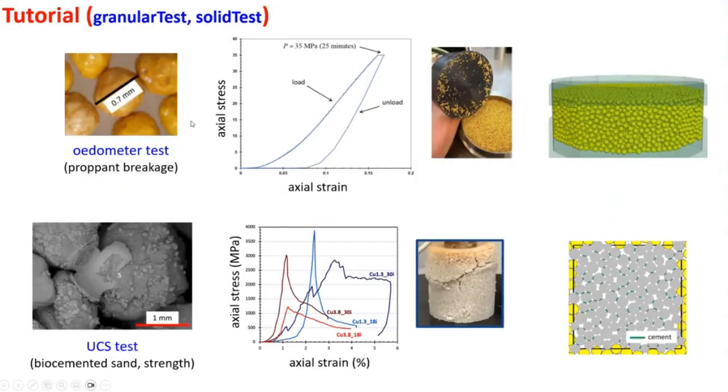We're going to turn that thing into an oedometer test, and we're going to bond it, and see if we can get this kind of a thing, right? The difference once we have this test set up is that we're going to take this material and add bonds, and then remove the sidewalls after we add the bonds. It's kind of fun. If you took this material and removed the sidewalls, it would all just fall out the sides. But if we add bonds and remove the sidewalls, now it's going to have a coherent shape, right? And then everything else is the same. We just push it and we monitor stress strain, right?